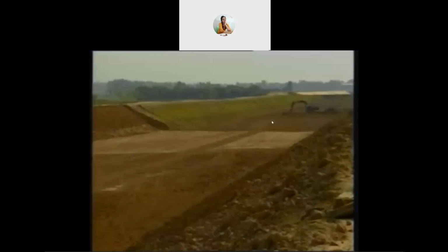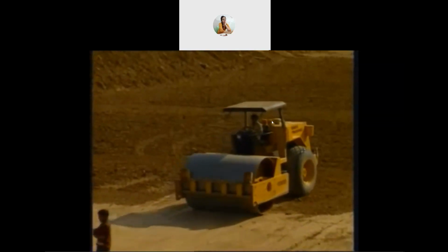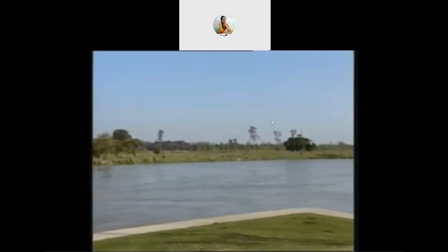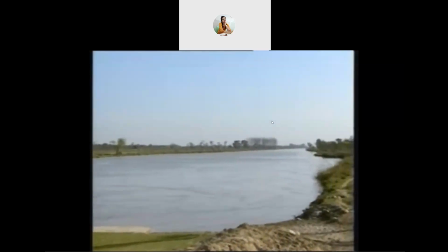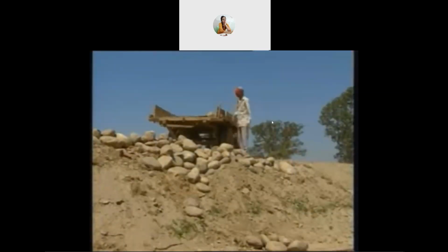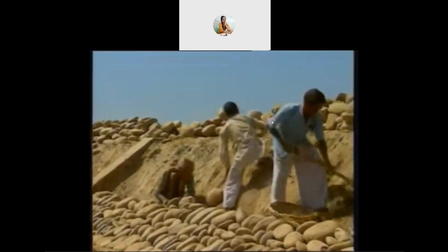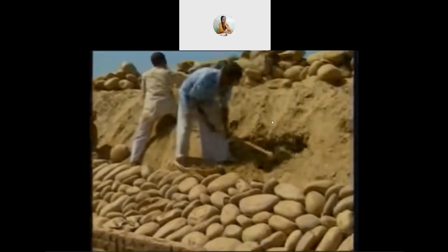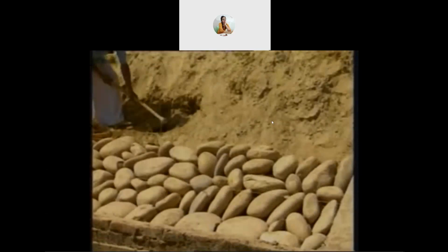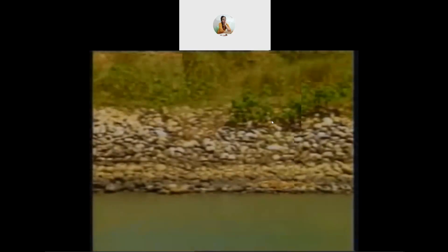Thick compacted earth lining may prove to be economical where suitable material for construction is available at site. Boulder lining is another economical lining where boulders obtained during excavation are readily available. It has very little flexural resistance or flexibility. Such lining is not satisfactory for canal infilling.